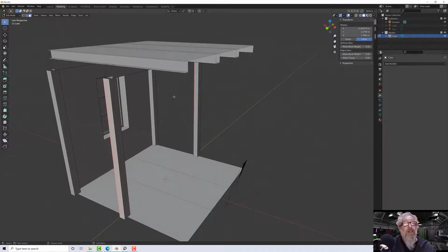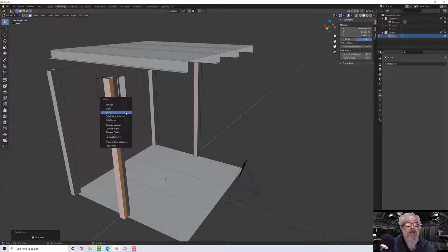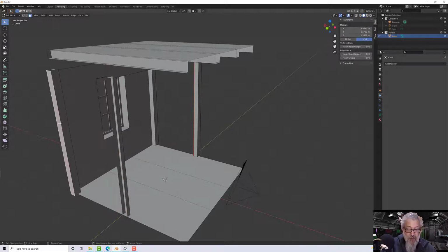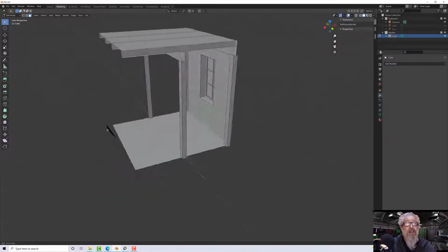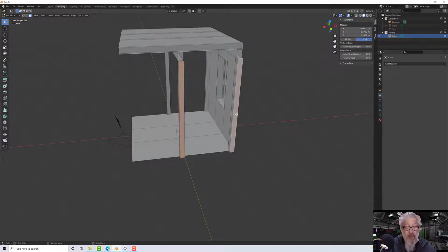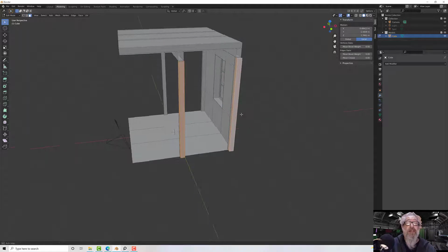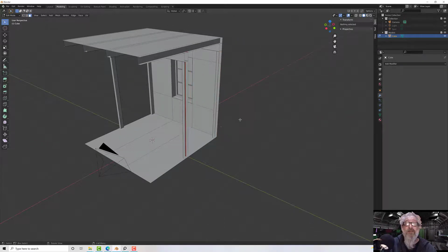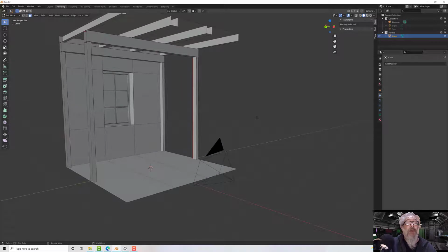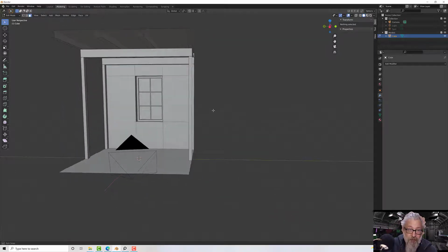Let's select this end and press Control and plus on the num key a couple of times until it selects up to half, and I'll delete those. Do the same here, Control plus, plus and plus, delete and faces, and then we'll do both these at the same time. So Control plus plus plus, whoops, and then delete. There we go. So now we've got some beams either side, which is going to hold the whole thing up, which is terrific. We want something to hold things up.